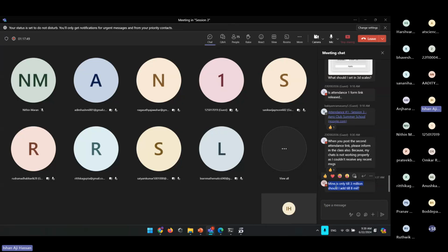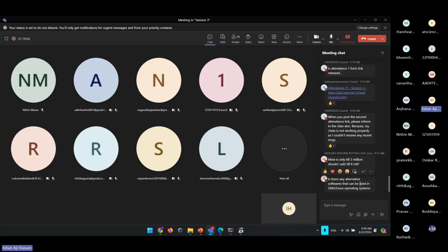I have added some extra Reynolds number ranges simply because we'll be using a higher Reynolds number for your wings. If you're using a higher Reynolds number, then you can add till later. But if the Reynolds number that you're using for your wing analysis is in the range of your batch analysis here, then you don't need to add anything else.